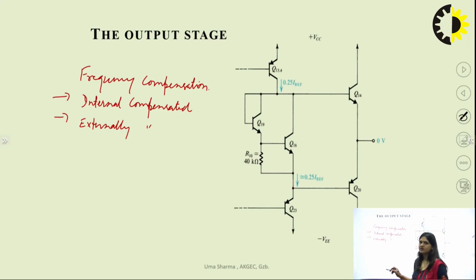So the IC 741 is an internally compensated IC, where we have used a coupling capacitor CC to nullify the effect of all the parasitic capacitances which are present in the circuit because of the parasitics of different transistors. As you know, the BJT has parasitic capacitances which are not required, and they will affect the frequency response of the circuit. So to avoid these undesired fluctuations, we have added a capacitor with a very small value to the IC that will look after all these parasitic capacitance effects. So the second stage is a gain stage, and along with it provides some frequency compensation.